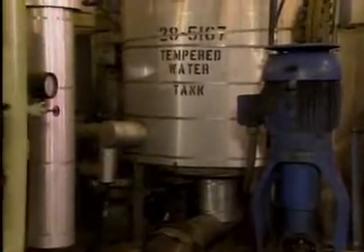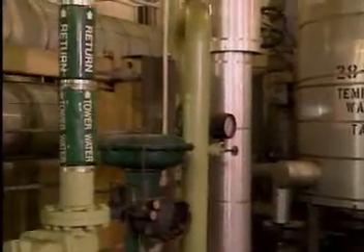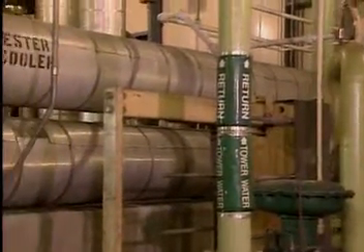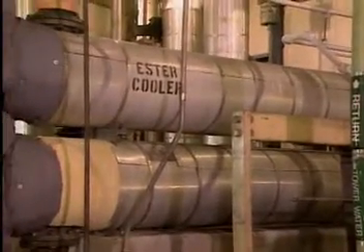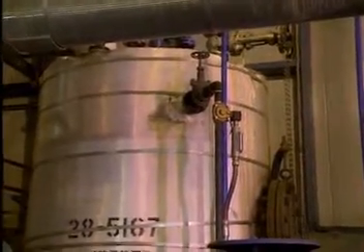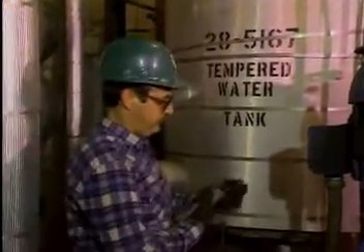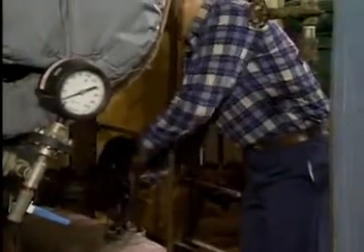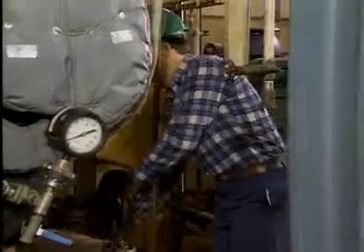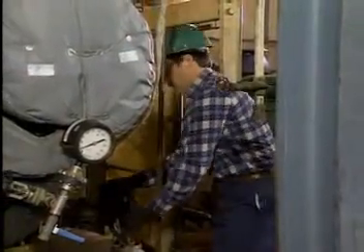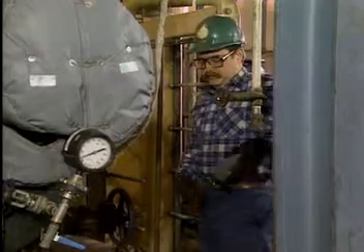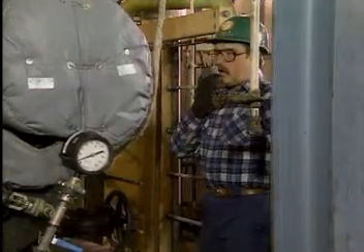When the cooling water pump is started, cooling water will fill the shell side of the heat exchanger. Any air that is trapped on the shell side escapes through the open vent valve. As the shell side of the heat exchanger fills, the operator listens for air escaping. When the shell side is completely filled, he calls the control room and has them shut the vent valve. Then the operator opens the shell side inlet valve the rest of the way. At that point, he informs the control room that the shell side is lined up and that they can establish the proper flow rate through the shell.